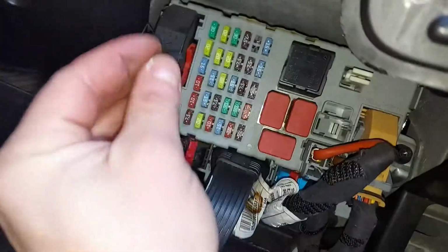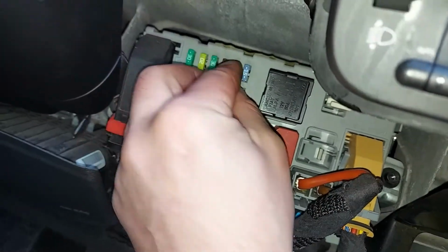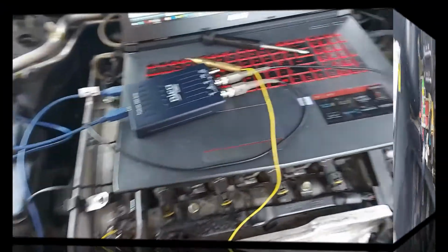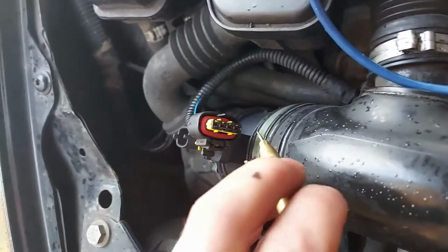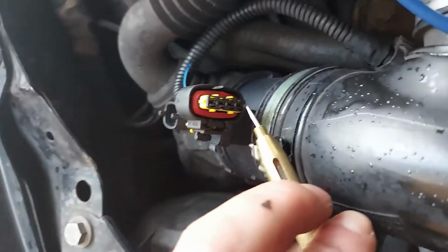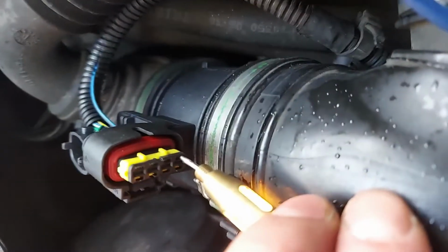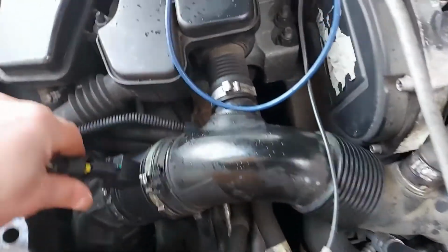So I've got a new fuse. Let's pop that in. Okay. Let's put ignition on. Okay, so now with the new fuse fitted, let's see if we get a voltage there. Let's gently touch it there. Olé! So we've got ignition. So that's very good. Could be that simple. That would be beautiful. Right, let's plug this back in.